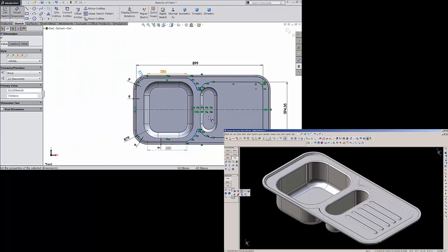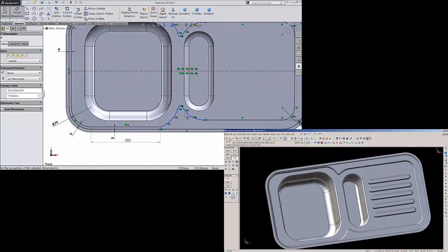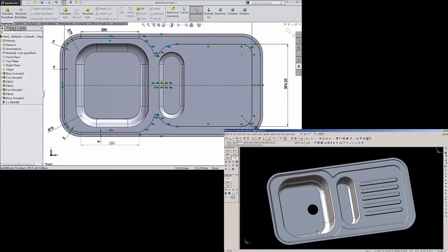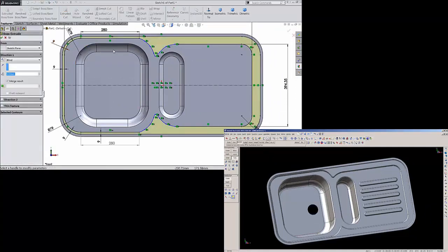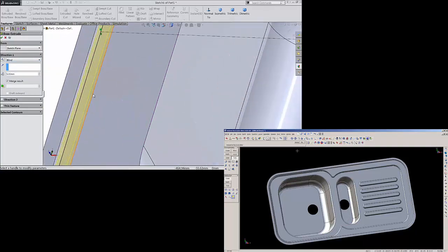Okay. Now this ellipse, this spline, you can define it also, but I don't want to waste that much time, so let's go and select here extruded boss. See this portion extruded, and extrude only up to 5 mm, a small thickness, you can see here. Okay.